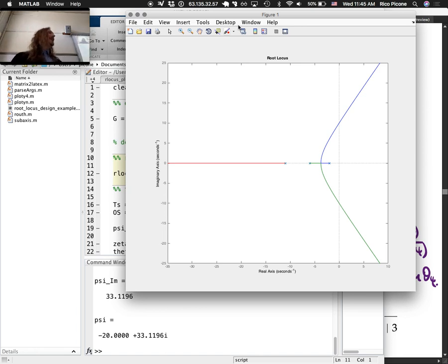It's not even close, our root locus is way down here. There's no way to even get close. So I'm not going to bother trying to get close with a gain here. You could try with our proportional controller, but there's no point because we're not even in the ballpark. You could get percent overshoot right because it's the angle, but there's no way we could get settling time. We'd be off by a mile.